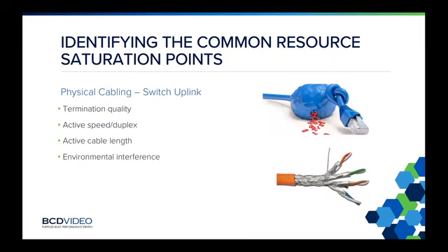From the edge camera switch in, once again, between each one of the switches, you always want to assess the quality of the cable length associated with it. The termination, active speed duplex, length of the cable, and is there any environmental interference that could be causing problems.